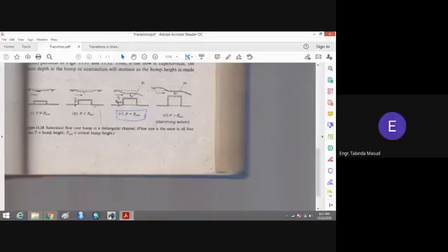Why? Because the critical depth is the depth of flow at which specific energy is minimum. We know this from the specific energy diagram, that at this depth of the flow we have the minimum specific energy for a given discharge. So the energy cannot be further reduced, and we cannot have a further reduction in the depth of the flow. So what will happen?